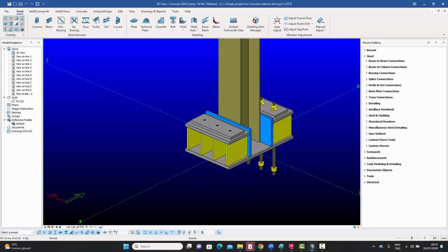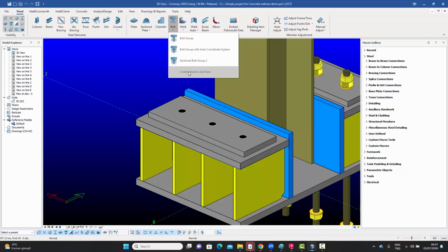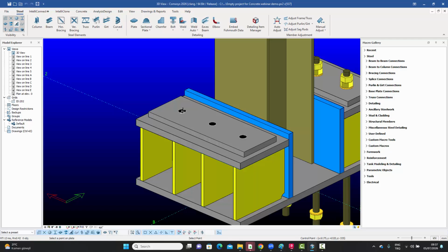You just show it a point, for example. So if I were to go into my command right now, I'll hover over this. It works in the negative Z direction. Sorry, it works in the positive Z direction. So it's a good idea to first place your work plane in the negative, so that it points downwards rather than upwards.